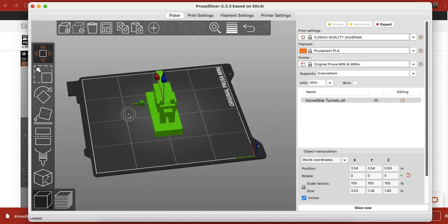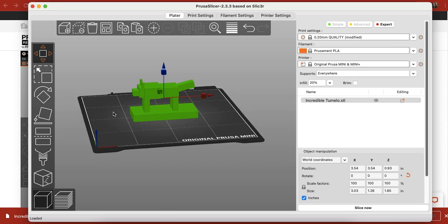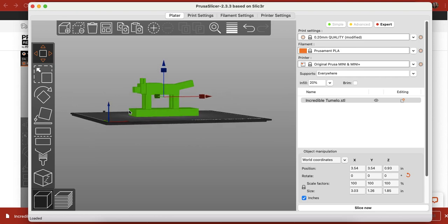Now let's say that I was creating something such as a hook. If I was 3D printing a hook, I might need a higher density. A high density would be anywhere from 50% to 100%. However, check with a Makerspace staff member to review infills if you are concerned about what kind of percentage you should use. Oftentimes, a print doesn't need 100% unless you have a very specific reason to be using it. So, anytime you think that you may need to go 50% or above, go ahead and talk to a staff member.